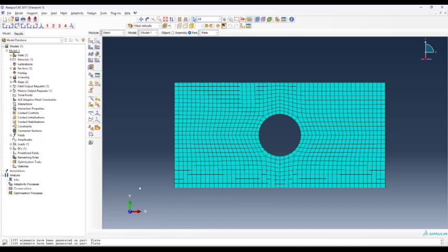Okay, that makes sense to everybody what we did? Instead of a free mesh where it went kind of all the way across and had to deal with this individually, we meshed 4 individual sections separately, symmetric ones, and we got a much cleaner mesh as a result. That cleared everybody? Any questions? Okay, so that was all we really needed to do at that point.